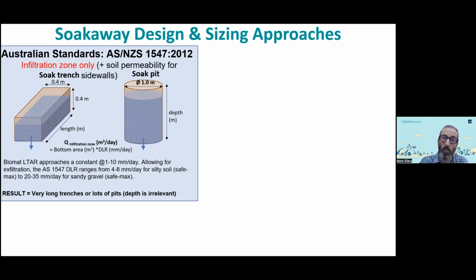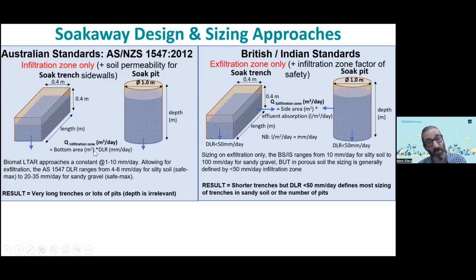This results in extremely long trenches or lots of pits because they don't make any allowance for sidewalls. And what we realise is that the sidewall is quite an important means of percolation or release of effluent through soakaways. The British standards do the opposite.